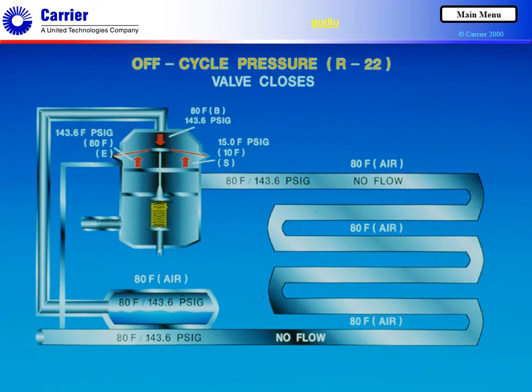As we have shown, the conventional thermostatic expansion valve uses a remote sensing bulb that always has some liquid refrigerant in it. This may cause problems during the off cycle as well as at system startup, especially for air conditioning applications. When a compressor cycles off, the liquid refrigerant remaining in the evaporator continues to boil for a time. If the compressor doesn't remove the vapor produced by this evaporation, the pressure within the evaporator quickly rises. It will stabilize at the pressure that matches the temperature of the air surrounding the evaporator.